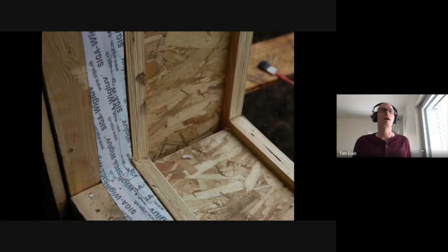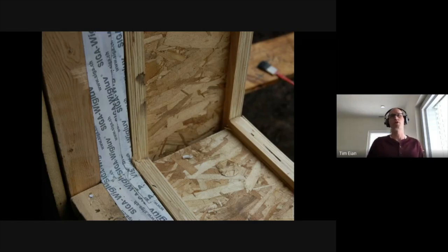Wood construction, this one here on the left-hand side, the part with the tape on it would be a 2x4 or a 2x6 structural frame that is air sealed to a sheathing material that is used as the air barrier. So this is our rough opening, and then a TJI or I-joist is used to make a secondary wall cavity for more insulation. So this is shown here at the window installation, but this is a great way to think of wood construction. How do we get from the 2x6 box to a super insulated box, air sealed? This is one way you can do it.